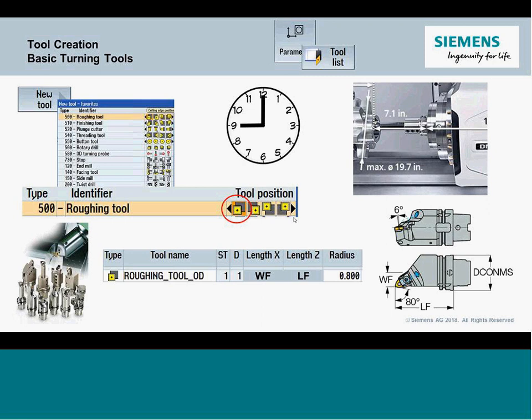I'm going to build the base orientation of the tool, a left-handed tool, in this primary configuration. Then use the third orientation field over, which would typically be what I would have done for a boring bar. The offsets, everything is going to work off of a gauge line. Typically what you see in these machines is HSK 60 or some HSK mount.